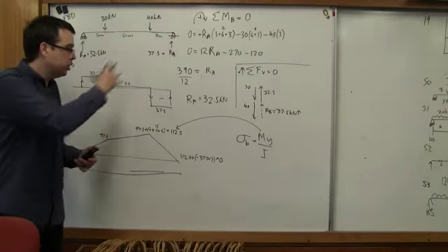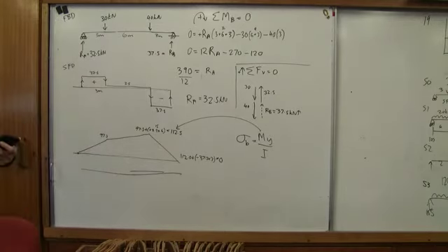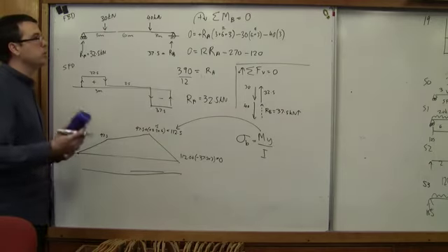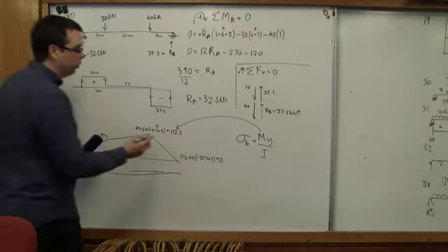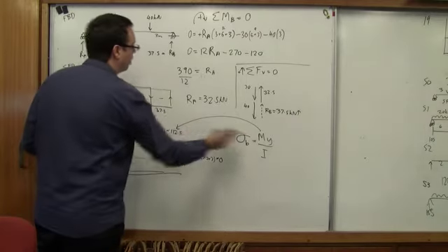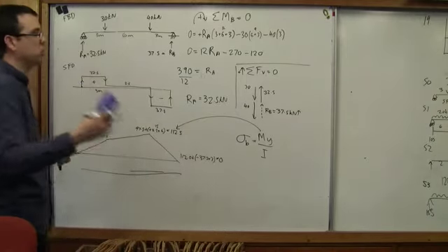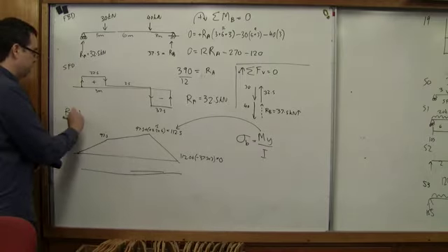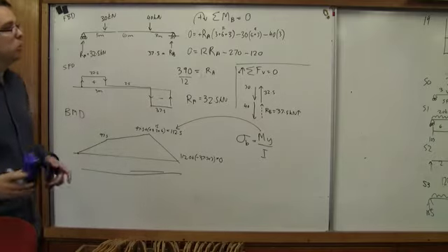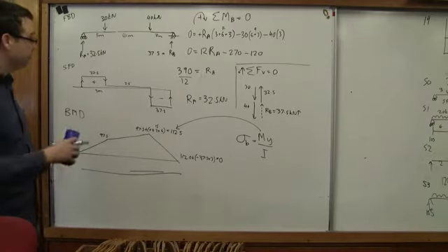Also, we might redesign our loads. We might reposition where things are going to be. We might add another wall to add in another support. Those are the reasons why we use these diagrams. But mainly from a mathematical point of view, we want to find maximum values so that they can go into our bending stress and shear force equations. Okay, I'll just clearly label this as a bending moment diagram, and we're ready to move on to question 51.